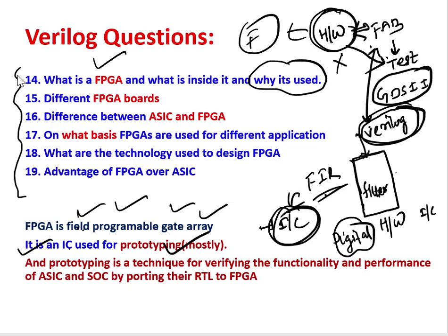So what is done in the industry is, before the GDS2 file, not exactly the Verilog code, is sent to fab, the Verilog code that you have written is tested again and again to check the functionality of your required logic. And how do they check that?